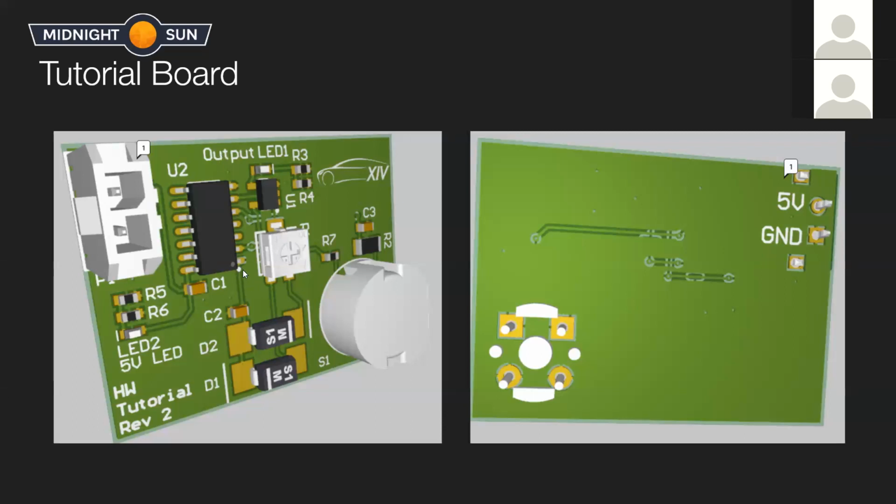This dot will line up to pin 1 of your IC, because generally ICs will have a dot indicating pin 1. Another thing you might notice is that on some of the ICs, we generally will use a rounded pad for pin 1. We'd round just the first one and keep the other ones square, just so it's easier to identify which one is pin 1.